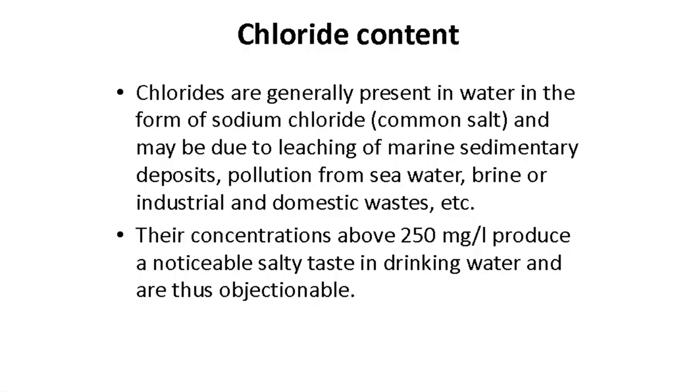Then we have another chemical property, which is chloride content. Chlorides are generally present in water in the form of sodium chloride, which is common table salt, and may be due to leaching of marine sedimentary deposits, pollution from seawater, brine, or industrial and domestic wastes. Their concentration above 250 milligram per liter produces a noticeable salty taste in drinking water and is thus objectionable.